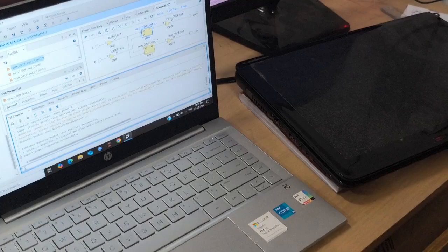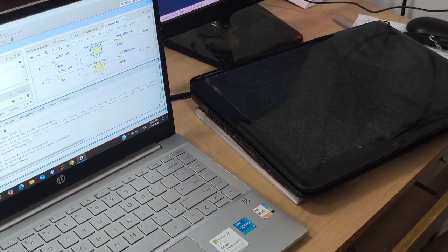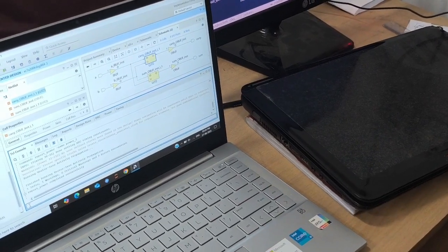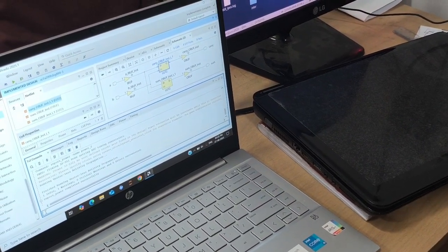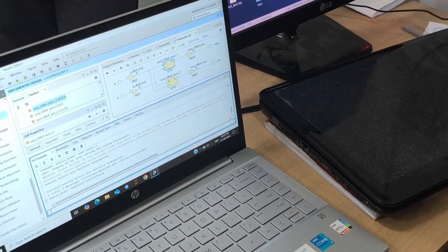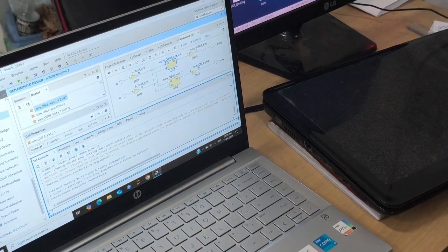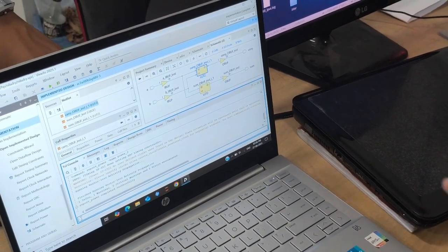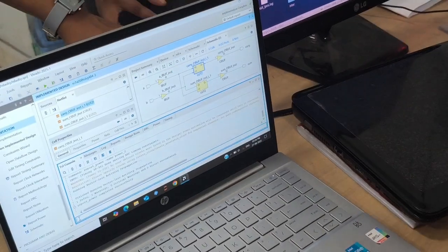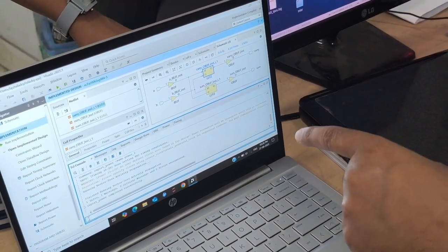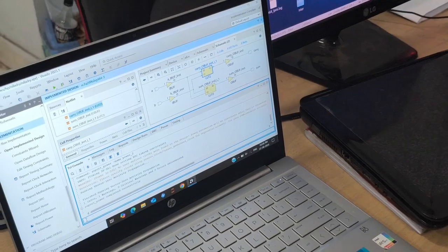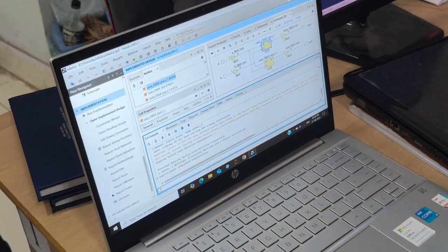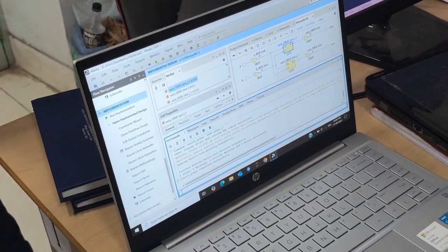That file contains the switching activity of the simulation. That means whenever the capacitance is charging and discharging, within the entire simulation of the half adder, how many times the capacitor is charging and how many times it is discharging, that record is there in the SAIF file. So the actual events will be placed in the entire circuit; not all the signals are on at a time. Only at a particular time, a particular signal is on.